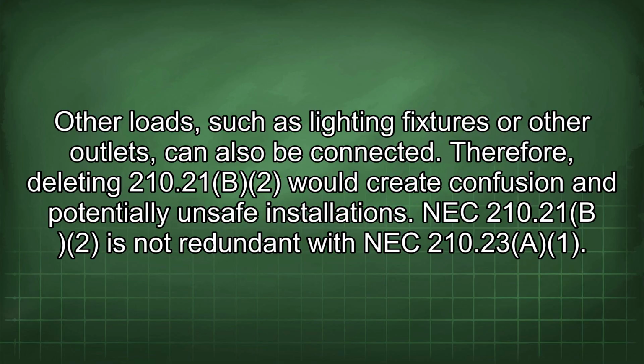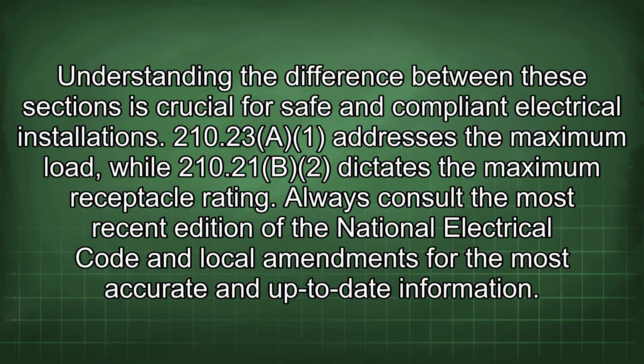NEC 210.21(B)(2) is not redundant with NEC 210.23(A). Understanding the difference between these sections is crucial for safe and compliant electrical installations. 210.23(A) addresses the maximum load, while 210.21(B)(2) dictates the maximum receptacle rating.